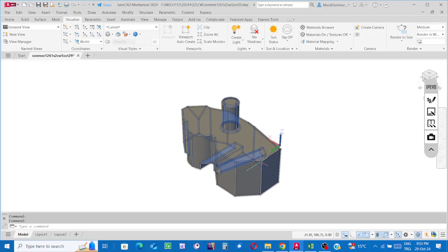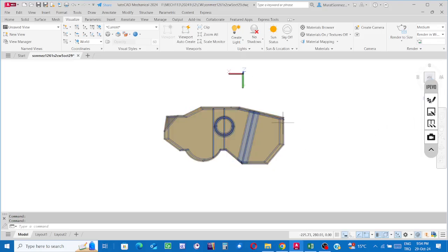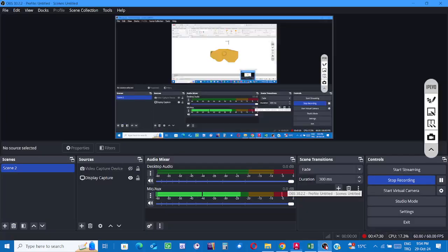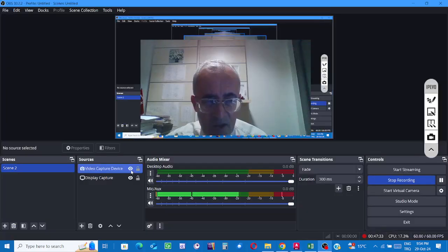For having an oblique surface at this corner, the inclination angle between this edge and the other edge is not 90 degrees. Since it is not 90 degrees, then in the method, we need to mark the corner points first and then apply the boundary line creation process, the 3D polyline process. Okay, after the break, you're going to see how. Okay, dear students, have a break now and then continue. Yes.